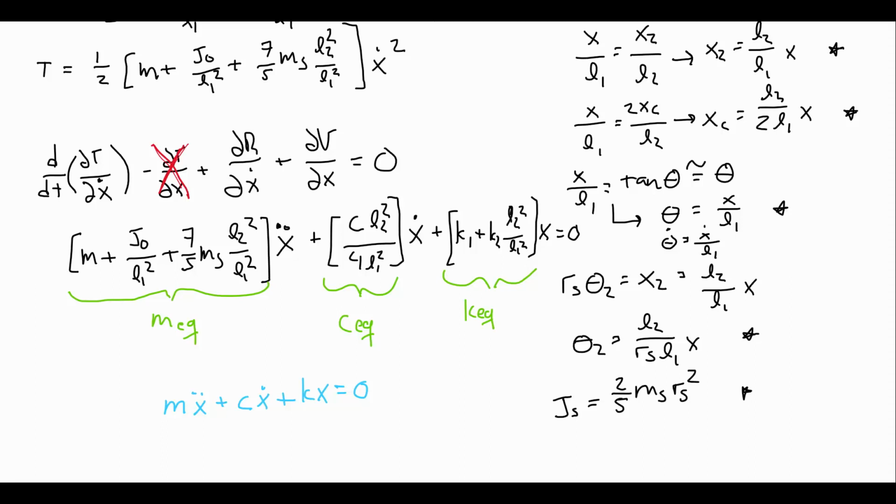And really, this is generically what undamped free vibrating systems, damped vibrating systems are going to look like in general. The answer we get out of the modeling is, what is the m, the c, and the k? Well, that's what we have above. So this is the equation of motion here, but specifically with these values of m, c, and k put in there. So that is the complete equation of motion for this system.